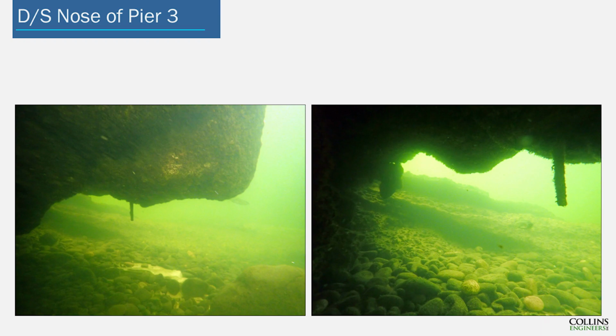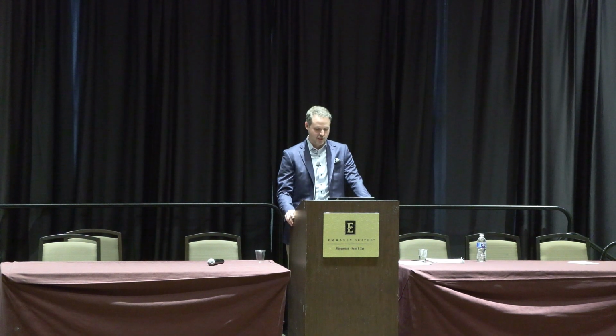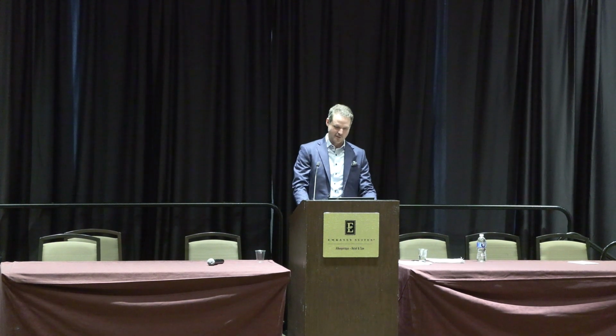So here are the photos of that now. For comparison to the sonar, here are two photos that I took of the void at the downstream nose. Note the rebar protruding from the bottom. That doesn't seem to be keyed into the bedrock anyway. And this void is actually large enough for me to basically swim under it to hide from the current and get a little rest while I'm diving. So it's actually a handy little feature for this pier. Helps inspection.